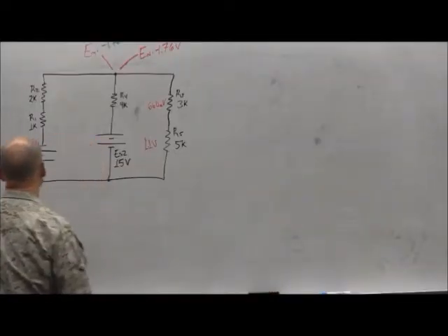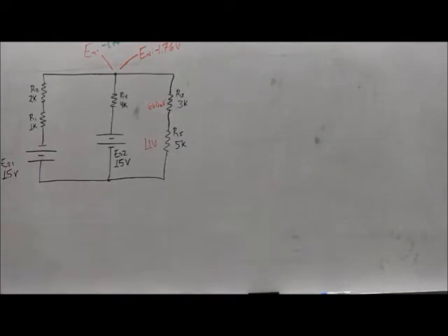Let's look at one more thing here. Let's look at current nodal. Can I use current nodal here? Yes, okay. I'll start off first by consolidating these two series resistors and making one equivalent resistance of 3K.